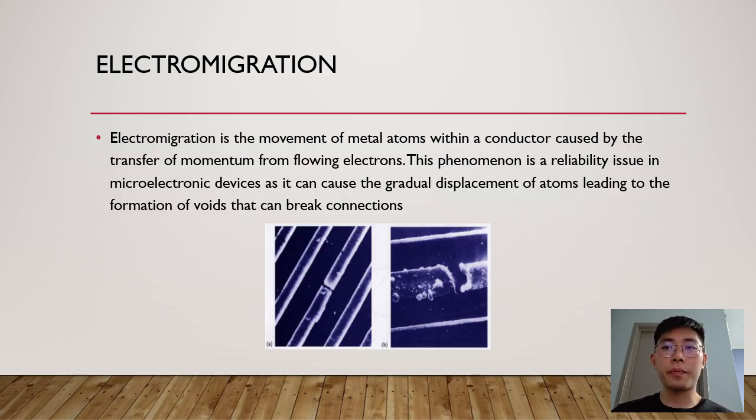So, this is a scanning electron micrograph of an aluminum interconnection. This is a failure caused by electromigration. The first is sputtered aluminum with 0.5 copper, and the second picture is evaporated aluminum with 0.5 copper. So there will be an explanation using the Black equation.